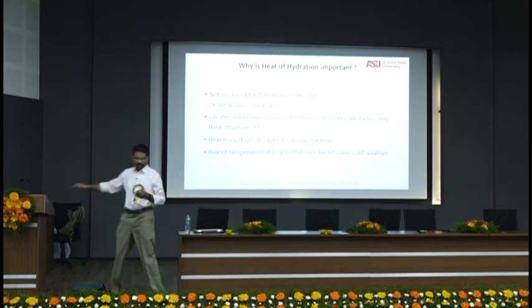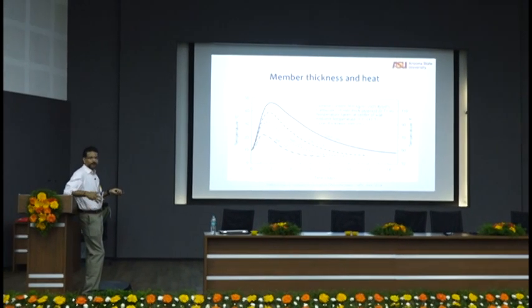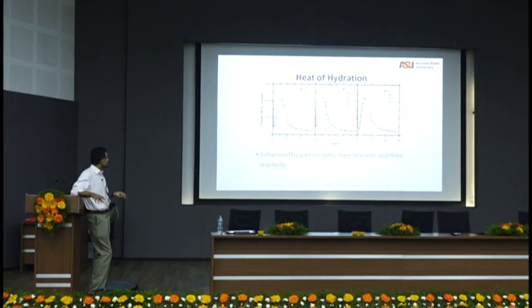Now, why is heat of hydration important? You probably have seen all of these. Member thickness and heat: thicker members, more heat. Thinner members, faster dissipation, so less heat. Now heat of hydration with different limestone contents.